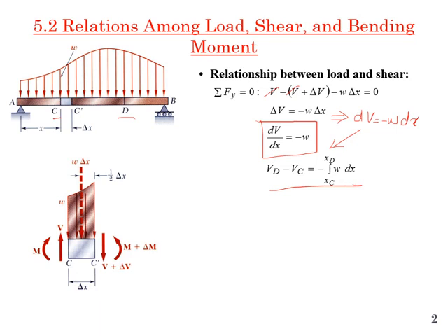Now, if you look at this expression, that is nothing but the area under the load curve. So it is nothing but the area under this load curve. And if I take the slope, it will give me the distributed load at that particular location.